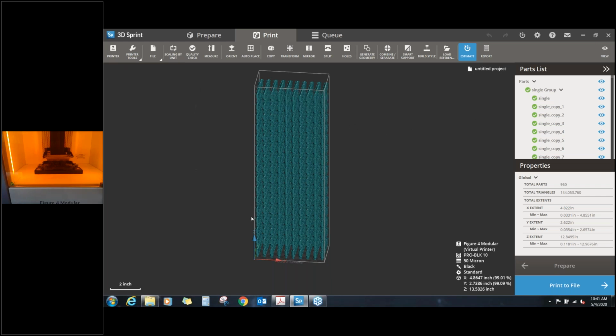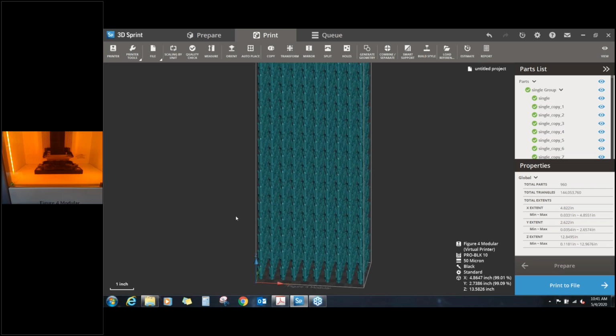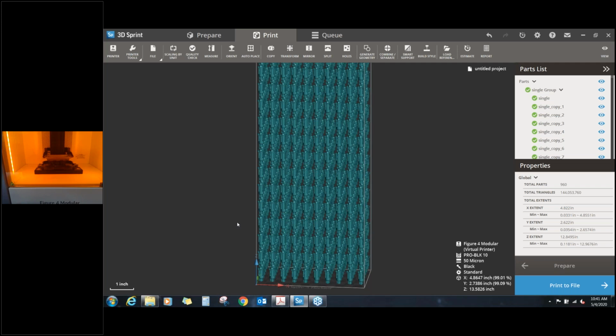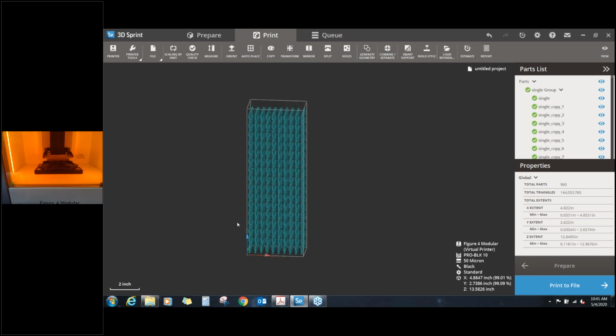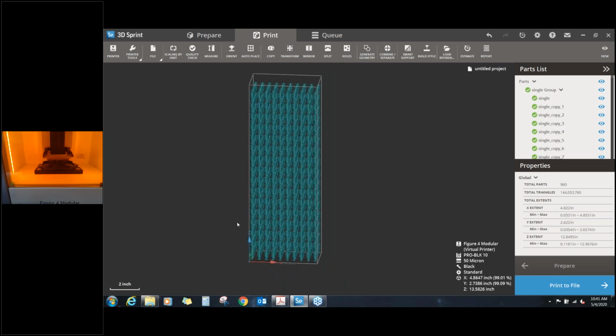So yes, I would still need to generate supports on all these parts. I'm going to spare you that time watching the software compute that because there's so many, but the build time will not change. It's still going to be right underneath the 5 hour range. So this gives you a nice example of why this is marketed as a digital injection molding alternative for geometries that can fit well within this envelope and work well with this cross-sectional area and the supports that this technology implements.